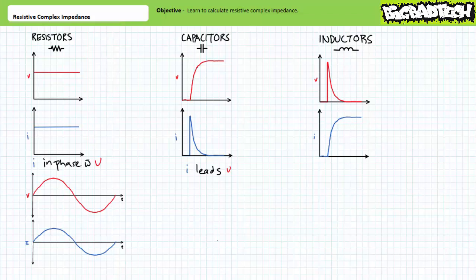Similarly, recall from our discussion on the time-variant DC response of inductors that inductors with no established magnetic field experience a voltage spike followed by rising current. This behavior can be summarized as current lagging voltage for inductive elements, and that the current rise occurs only after the voltage spike. As with capacitors, the time constant established by the inductive circuit under inspection determines how slow or fast this exchange of energy occurs. For purposes of time-variant DC analysis, we never really explored beyond these horizons.